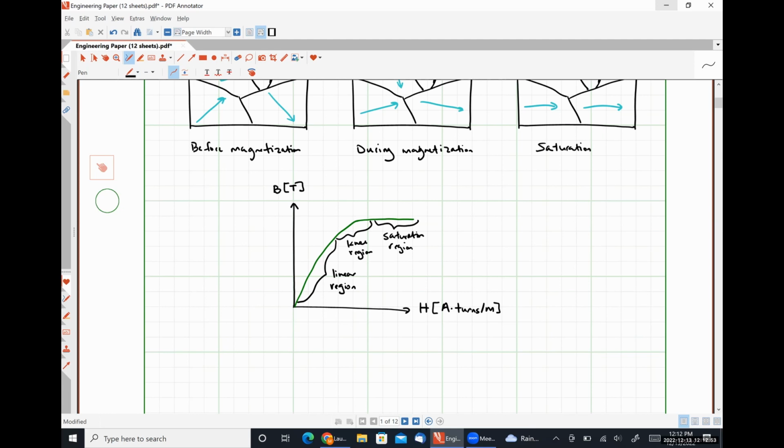Okay. So the handout that I gave you has the magnetization or BH curves for a couple of different materials. On the front of it, we have a magnetization curve for 1929 gauge steel and a soft steel casting for magnetizing intensities ranging from roughly 0 amp turns per meter all the way up to 8,000 amp turns per meter, and magnetic flux densities ranging from approximately 0.2 Tesla all the way up to 2 Tesla. On the back of the sheet, we have another set of curves from a different textbook for a few more materials: cast iron, soft cast steel, silicon sheet steel, and a nickel iron alloy. And they all behave roughly like this, just to relative degrees.